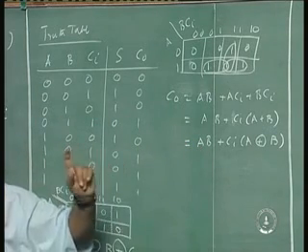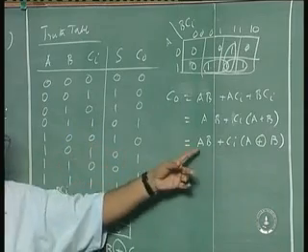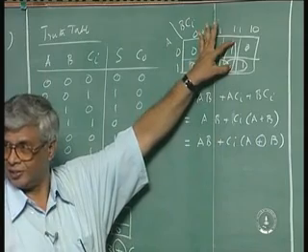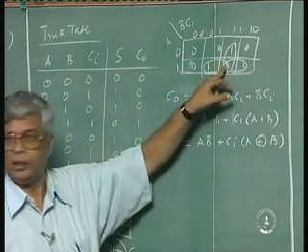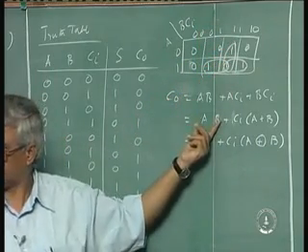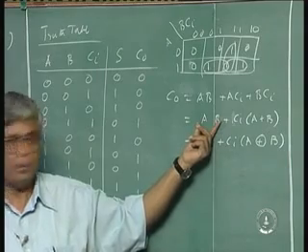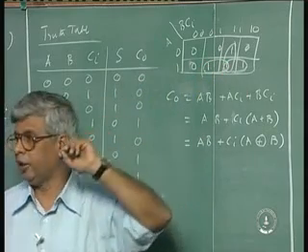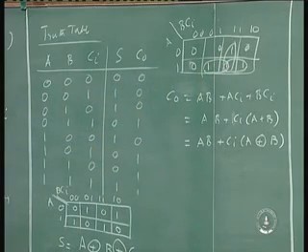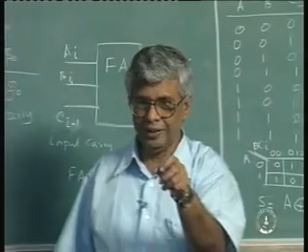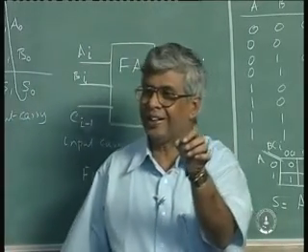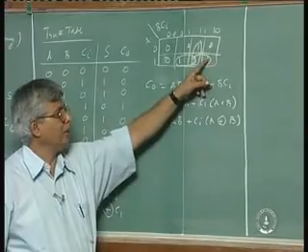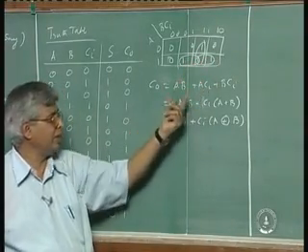I can tell you quickly, intuitively, without having to go through Boolean algebra, how this can be right. When you say AB, you are taking these two terms into account, right? This one and this one have been considered in getting this expression. Is that right? AB is same as this and this. I had this one extra one. In order to make my sum of product expression smaller, what I did was to combine this one with a 1 and combine this one with a 1. Remember, this one has already been considered in this expression.